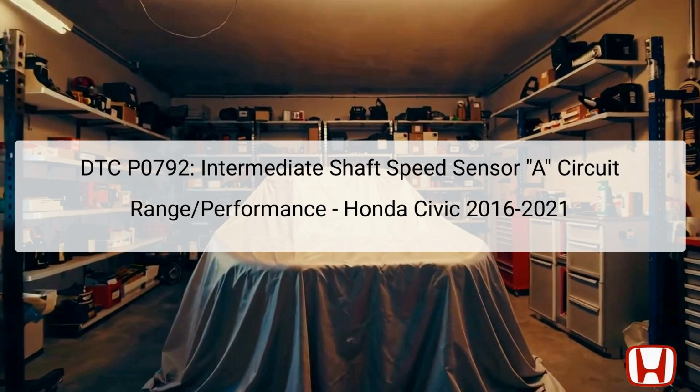It's important to note that this issue is electrical in nature and not caused by mechanical problems within the transmission itself. Understanding this distinction is vital for effective troubleshooting and repair. Diagnostic trouble codes like P0792 require careful examination of related components and electrical circuits to ensure proper functionality.